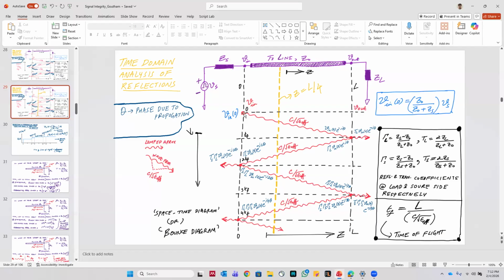See, I think there's a wave propagating here, and then it goes here, reflects, and comes back. Whatever wave is coming back is going to interfere with this wave. Then it goes here, bounces back, again interferes, and so on. The signal that reached here initially was Vn, and that signal is now there. But when the signal goes here and bounces back, that Vn, since it's already there, now gets added with this reflected signal, and then further added with the further reflected signal here, and so on.